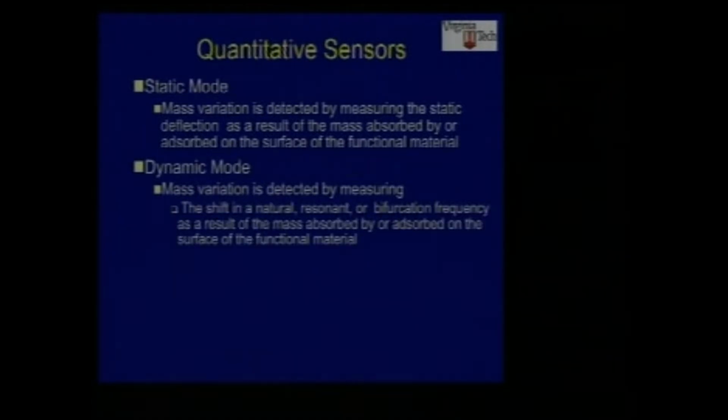You look over the shift in the frequencies. You have, for example, a cantilever beam. You add a mass to it. The mass increases, which shifts the frequencies down, so that you get the shift in frequency related to the mass of the material. Maybe that might not be as sensitive. You look over the resonant frequency. And if not, then you look over something which is horrible, bifurcation, and you look over the unsafe bifurcation, subcritical type bifurcation.